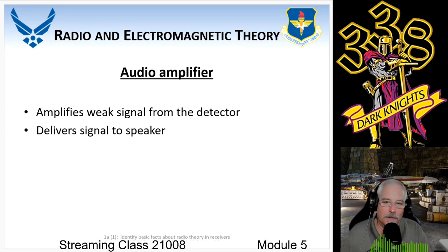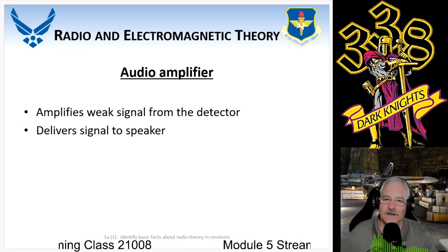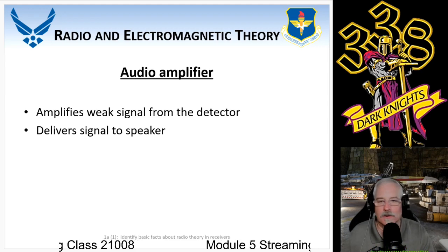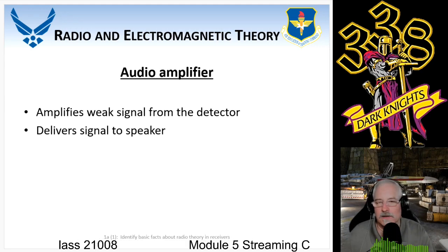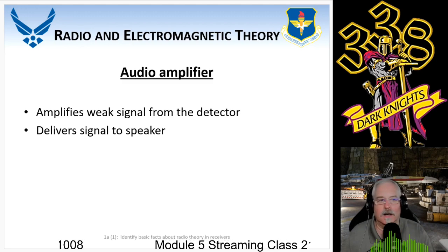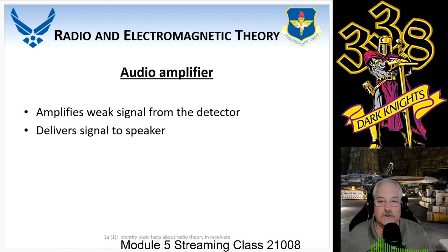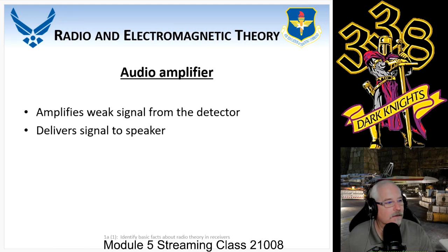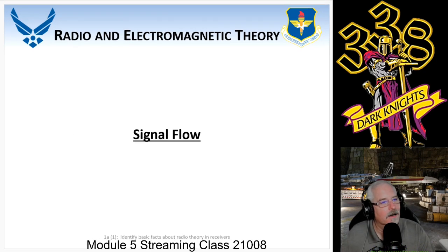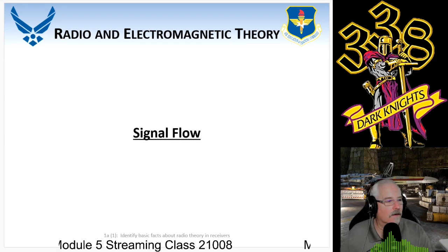It's normally anywhere between, I've seen as low as 4 ohms and as high as 600 ohms. Most of our Air Force devices are 600 ohms. Why? Because we have aircraft, and they will interchange the speakers. Kind of crazy, ain't it? Called money savings.